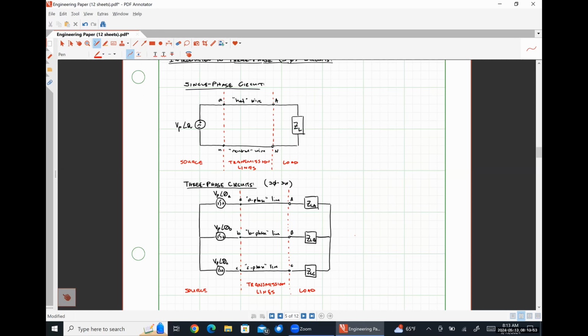The infrastructure costs in sending power over long distances and all of that kind of good stuff are significantly cheaper in a 3-phase system than they would be in a single-phase system, because it literally takes fewer wires to do it. That is the principal advantage of 3-phase power. Now, in the context of specific loads, if we were dealing with, say, an electrical motor, there is another extremely huge reason to use 3-phase power, okay?